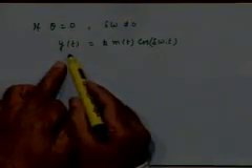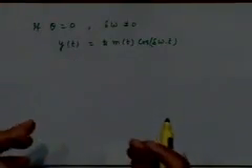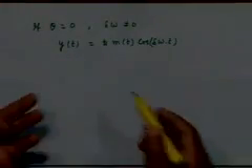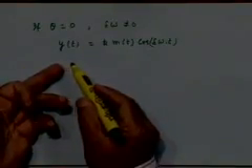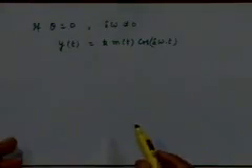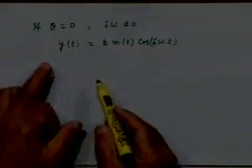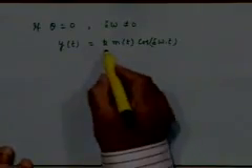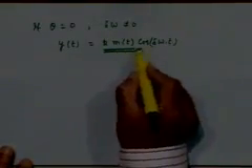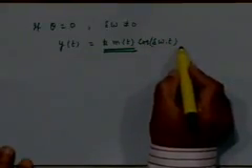When you take the Fourier transform, just a second. What Fourier transform? You are looking at the recovered signal y of t. Fourier transform only will tell you what is happening in the frequency domain, but this is what you are getting. Is that okay? After multiplying and low pass filtering, this is the output that you are getting, whereas what you wanted was k times m of t. So instead of getting what you want, you get that into something. If you pass it again to another low pass filter, this time I will be getting m of t.